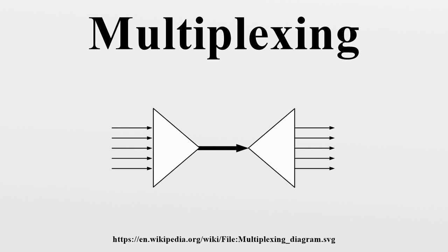Each terminal communicated at 2400 baud, so rather than acquire 4 individual circuits to carry such a low-speed transmission, the airline has installed a pair of multiplexers and a pair of 9600 baud modems. One dedicated analog communications circuit from the airport ticket desk back to the airline data center is also installed.